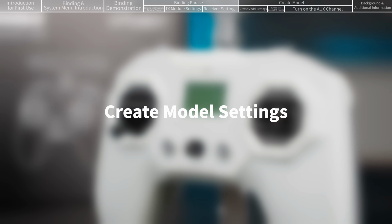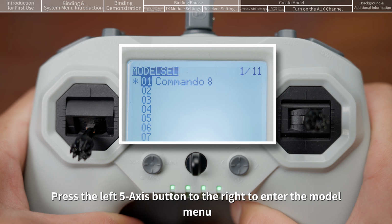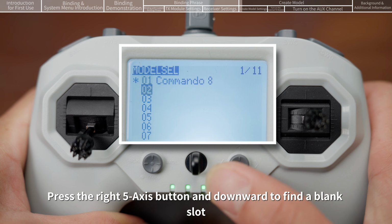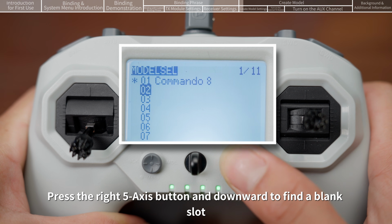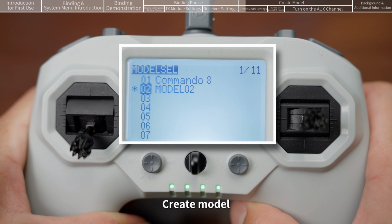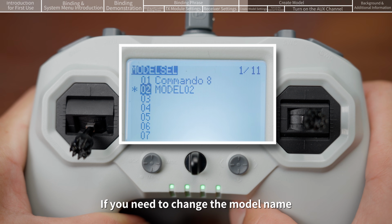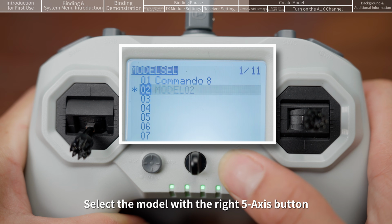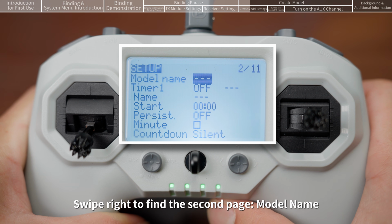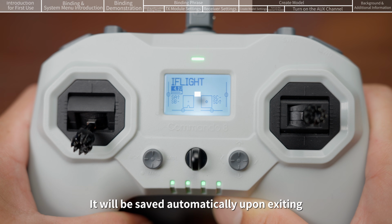Create model settings. After the remote controller is powered on, press the left 5-axis button to the right to enter the model menu. Press the right 5-axis button downward to find a blank slot. Long press the right 5-axis button. Create model. After creating the model, the name is set to default. If you need to change the model name, select the model with the right 5-axis button. Swipe right to find the second page, Model Name. You can set the name according to your needs. It will be saved automatically upon exiting.